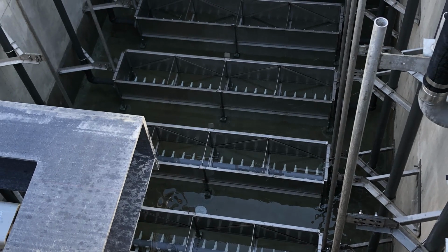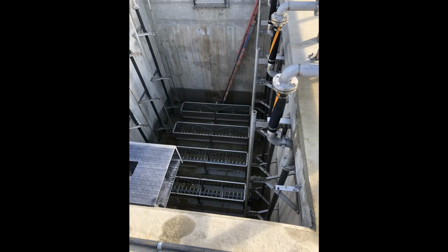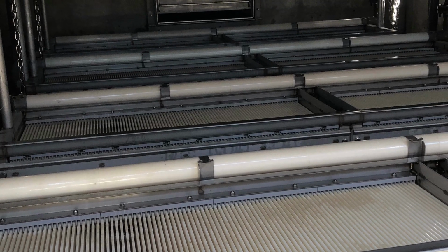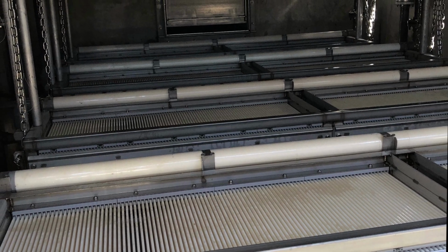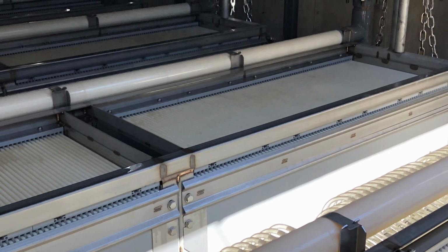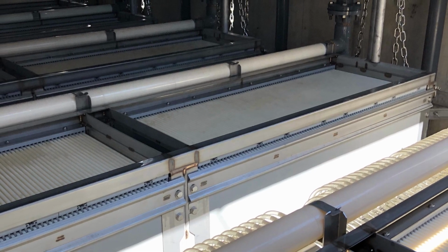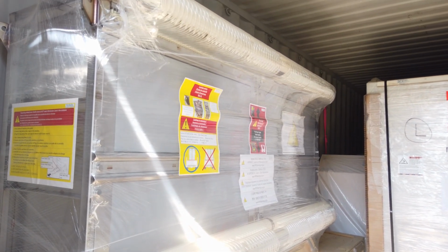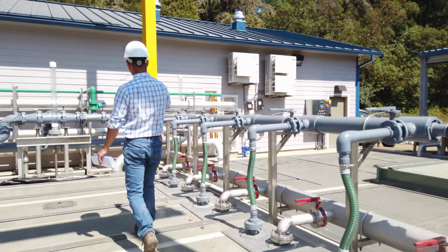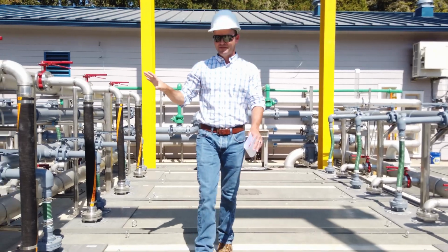The membrane system consists of a coarse bubble diffuser system at the bottom of the membrane units. This provides not only air for additional biological oxidation, but primarily for scouring of the membrane surface. As the water is pulled through the membrane, solids are pulled onto the surface. Air scour is needed to remove solids from the surface of the membranes and maintain a proper flux rate. The air and mixed liquor flow through the membrane cassette much like an airlift pump, creating a well-mixed environment in each tank. Air is delivered to the coarse bubble diffusers from the stainless steel air piping.